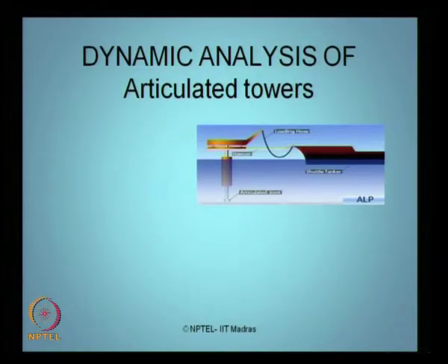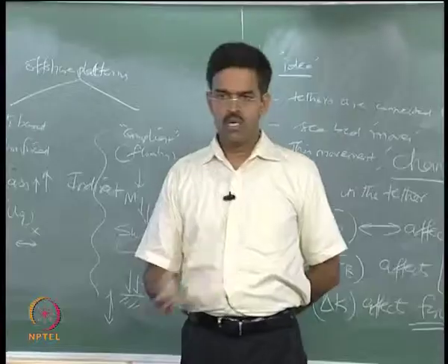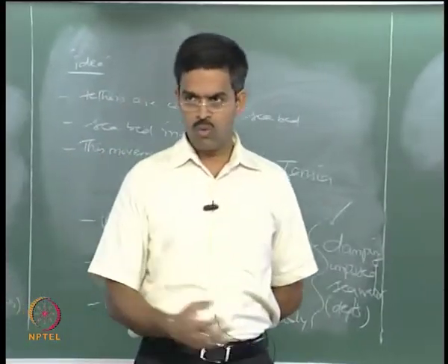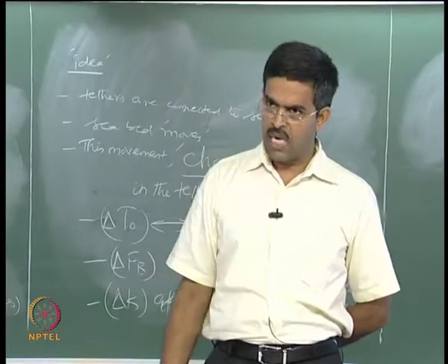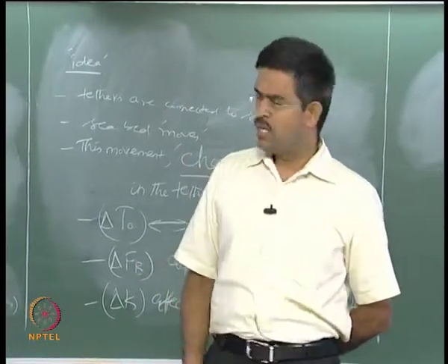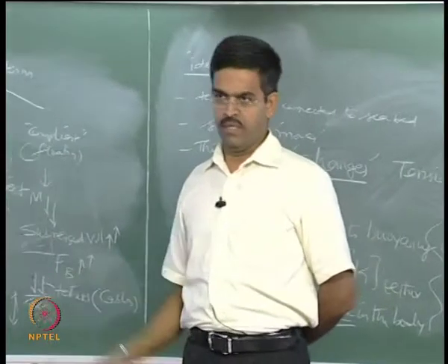If you want to create an inspection base in sea, I go for ATs, because AT installation and decommissioning are very simple, and they can be mostly reusable. And if you want to hold down a big tanker in the sea during the FSO, floating storage offloading process, I have DPS, dynamic positioning systems. In addition to that, I anchor the shuttle tanker with an AT.